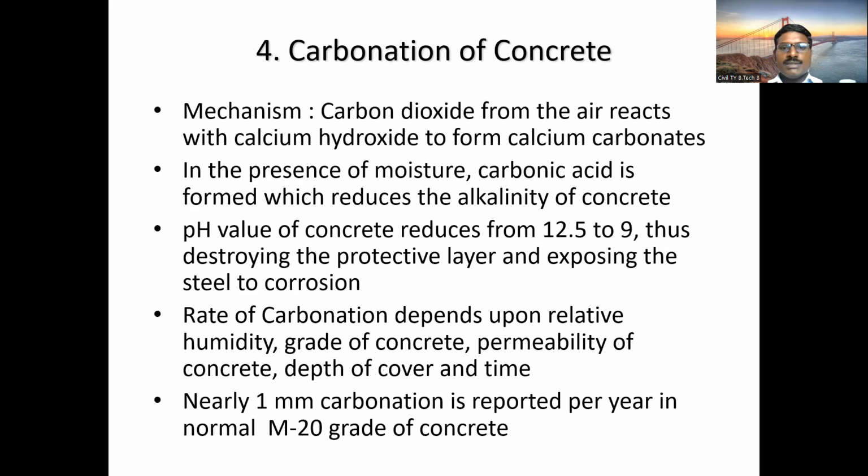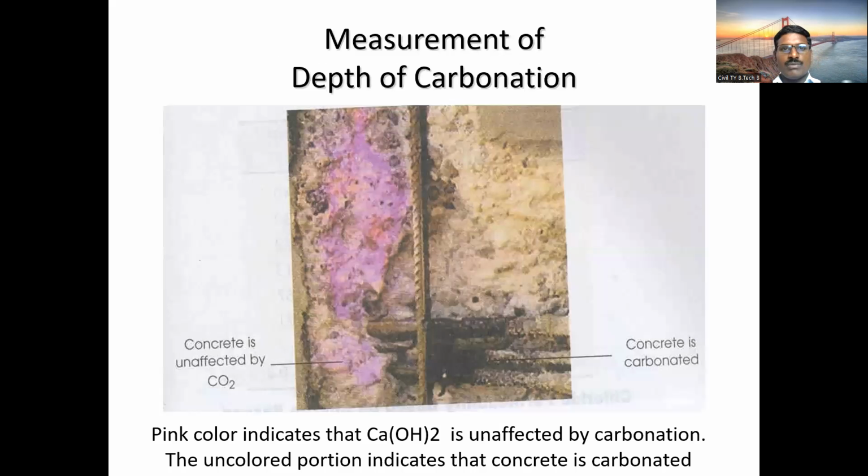The rate of carbonation depends on the relative humidity and grade of the concrete, also the permeability of the concrete and depth of the cover. Nearly 1 mm carbonation is reported per year in normal M20 grade concrete. So this is about carbonation of concrete.